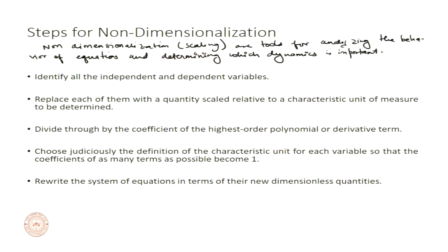non-essential. For example, if we take honey versus oil and we drop both of them. In one case, which is viscous dominant, honey has a high viscosity compared to oil. In that case, the shear terms are more dominant in a Navier-Stokes equation compared to oil, in which case the convective terms might be more dominant compared to the shear terms. Right. So we make assumptions and we simplify a much larger equation into smaller equations which are manageable and which we can easily solve to get almost accurate results, instead of solving the whole equation. Okay, so how do we do this?